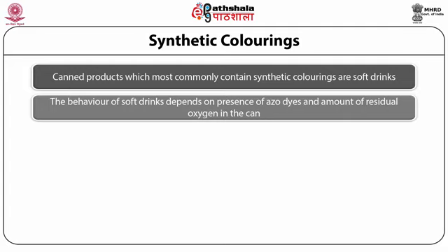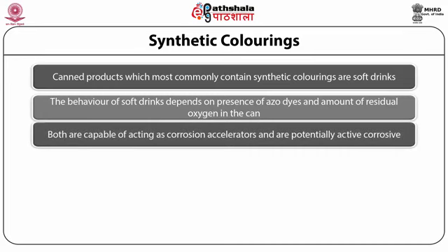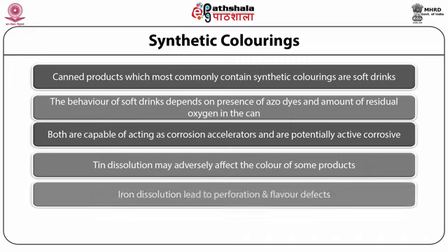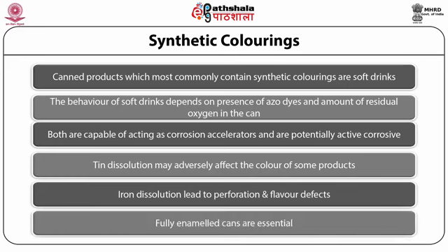residual oxygen in the filled can. Both of these components are capable of acting as corrosion accelerators and are potentially active corrosive agents. Tin dissolution may adversely affect the color of some products, and iron dissolution may lead to perforation and flavor defects. Thus, fully enameled cans are essential for the products which are generally manufactured with synthetic food colorings.